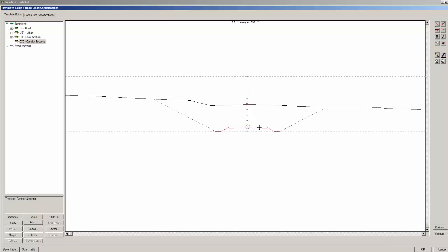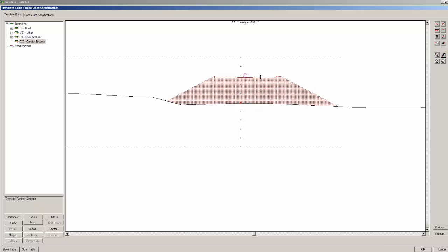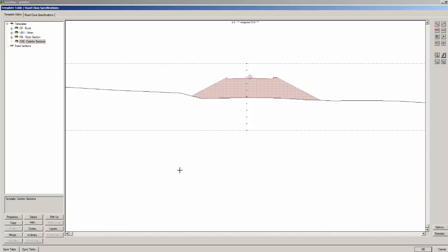So we have a smarter template. It's not perfect. Like maybe in here, it's not putting a ditch in. If we had sampled it more densely, we'd get better behavior. But it's starting to resemble a pretty good approximation of the volumetric quantities that are involved from that Civil 3D file.